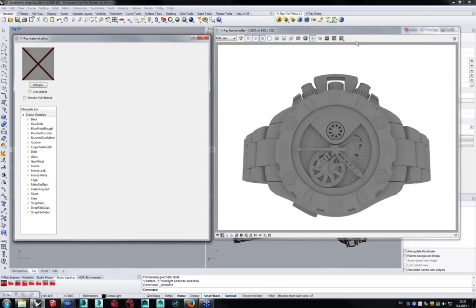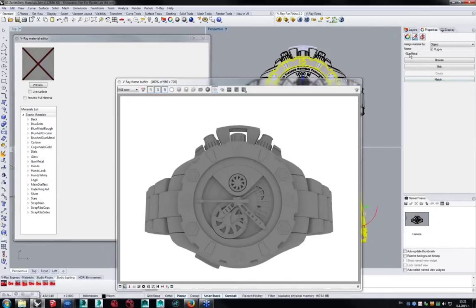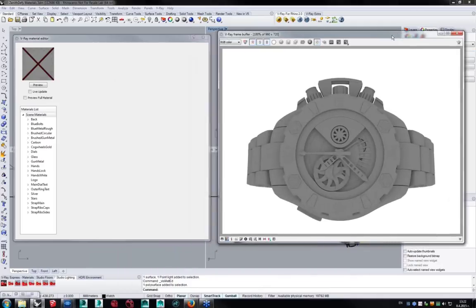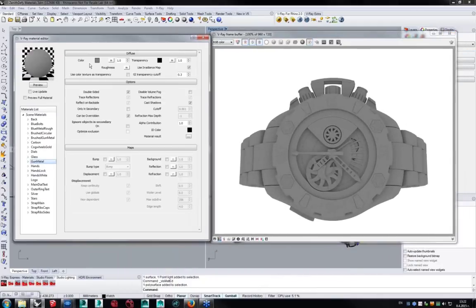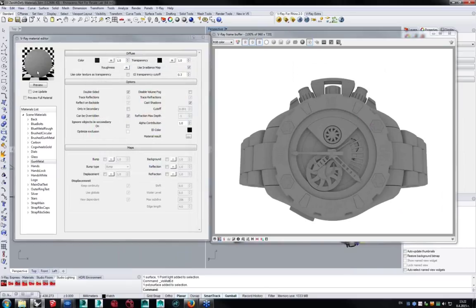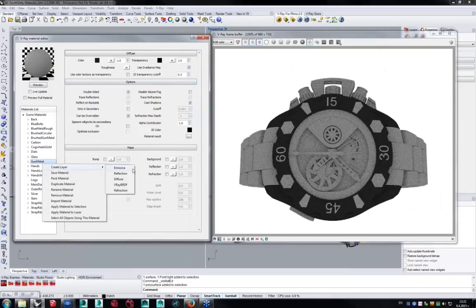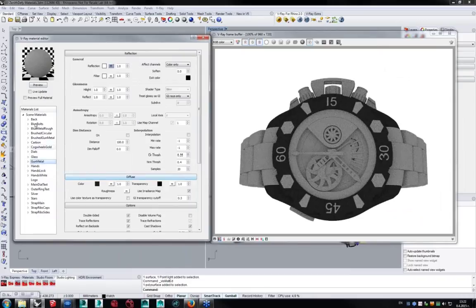And here this material for the front ring is called gunmetal, so I'll just select the gunmetal. And for metals, I will strongly suggest you use lower intensity values, like 30, so it's darker. There we go. And let's add reflection. So just create a reflectivity layer.